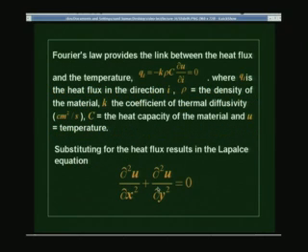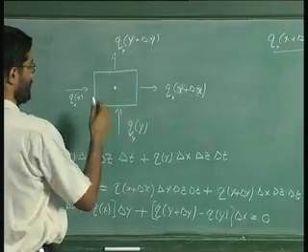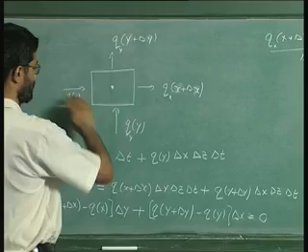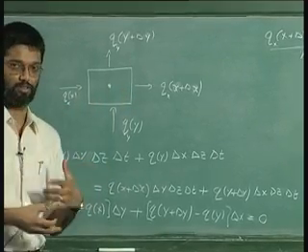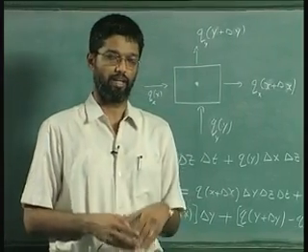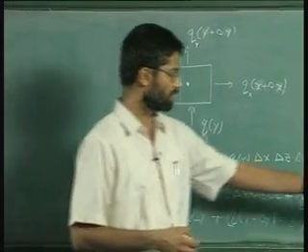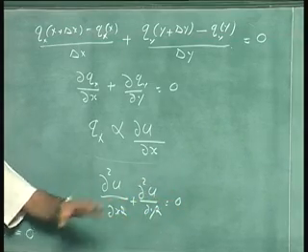Now in the case where there is a source, this equation would be Poisson's equation. That's also another example. We could have, for example, a particular source sitting there, kept at a constant temperature. So if you have the slab where the middle of the slab or some part of the slab is kept at a constant temperature, that's like having a source at that point. And then you have this equation here, with a source term on the right hand side.